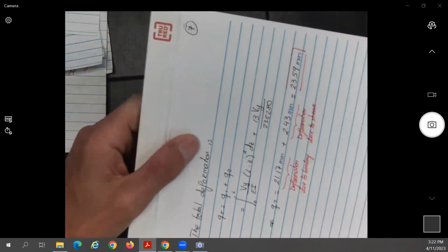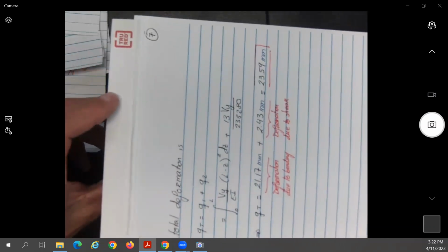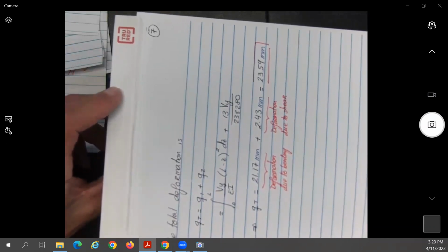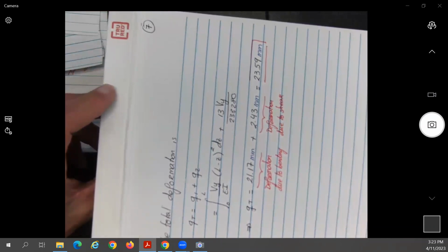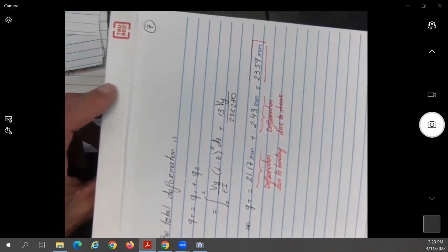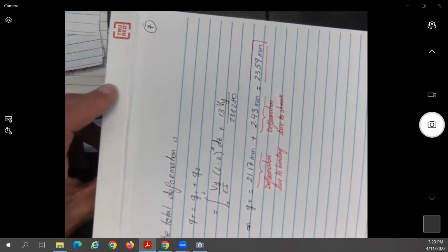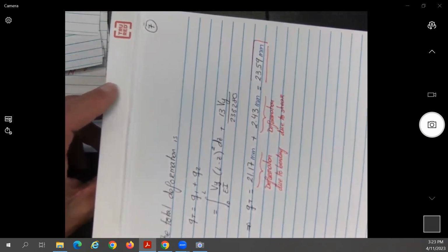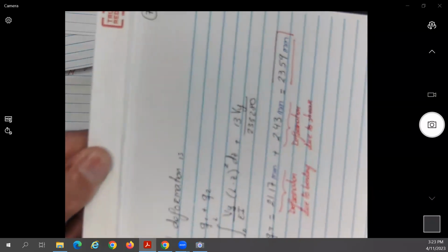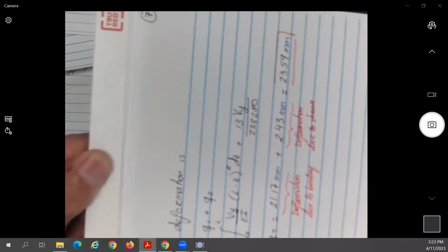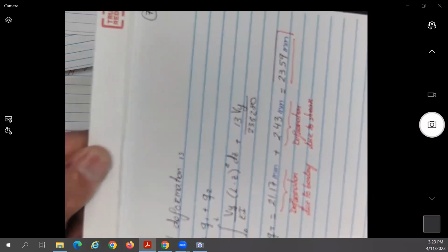Now I have a question for you, and this is what is difficult about buckling. Do you think buckling is a continuous problem, or is it a stability or instability problem? So for example, if I push over here with my hands, let's say I'm making up, okay, 1 Newton, is this going to buckle at 1 Newton? Let's say I do 2. Now here it cannot buckle, no? So it's going to buckle at 2. So it either buckles or does not buckle, correct? So it is a stability problem.